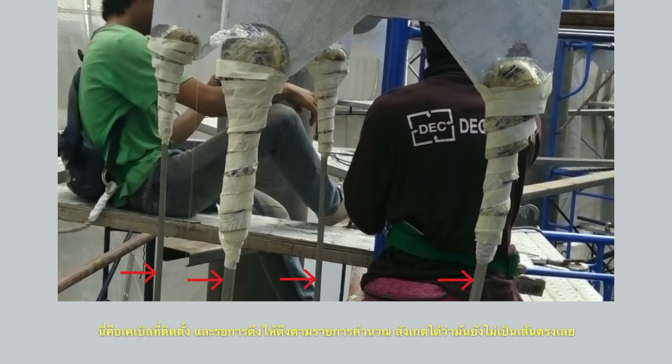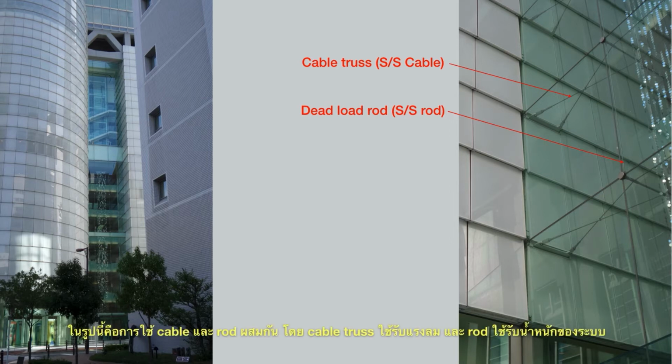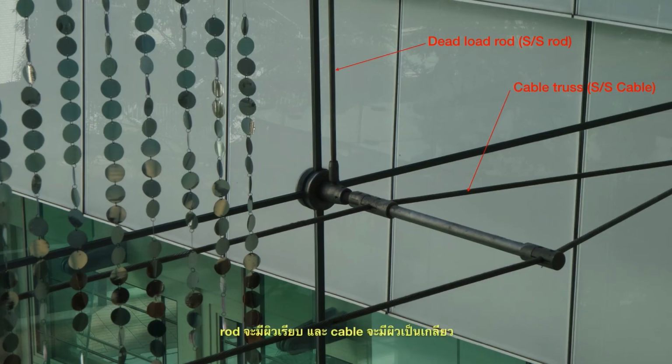This is a picture of cables installed at the ear plate waiting for pre-tensioning. You can see that they are not even in a straight line yet. In this picture, the cable is used as a cable truss system to withstand the wind load, while the rod is used to support the glass dead load. You can see the texture of the strand at the cable truss, but the rod which is supporting the dead load is smooth on the surface.